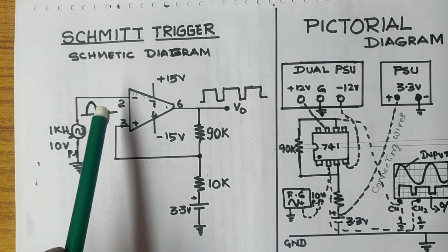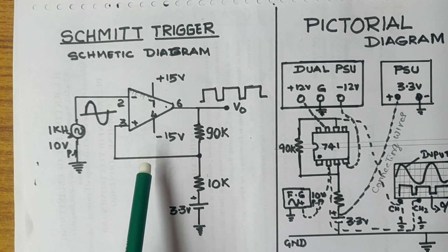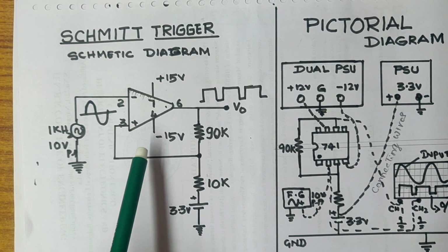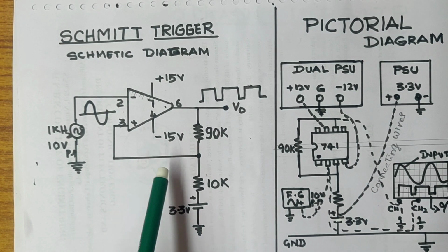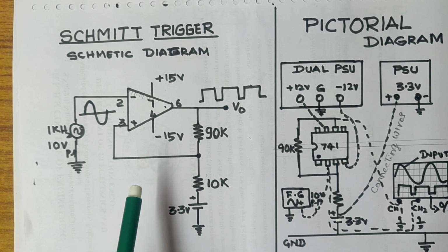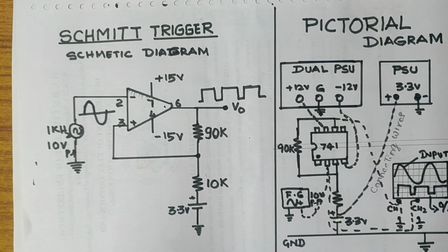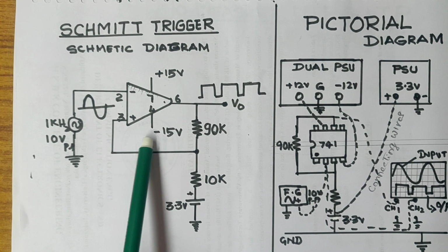The main applications of the Schmitt trigger are interfacing signals between analog electronics and digital electronics, and translating levels within different logic families. One major problem encountered during this process is the pickup of noise. Digital signals are inherently fast because they deal with high frequency and fast rising and falling edges, whereas in analog the changes happen at a slower pace in terms of rise and fall times.